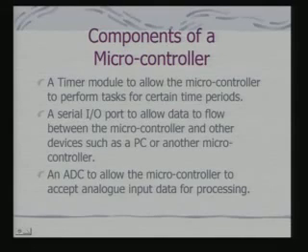On top of parallel I/Os, we have serial I/O ports which allow data flow between the microcontroller and devices which support serial interfaces. The serial ports are also used for interfacing with the PC during the development environment and development life cycle of the embedded system. As well, when we need to use the embedded appliance with the PC, to read data or reprogram it, the serial port is also used.